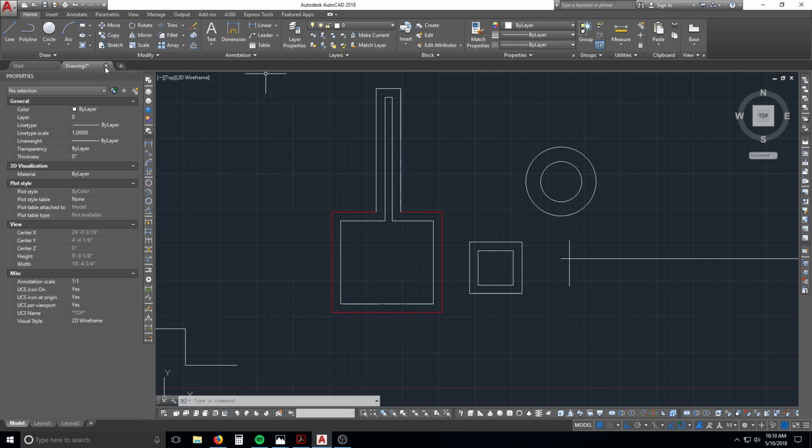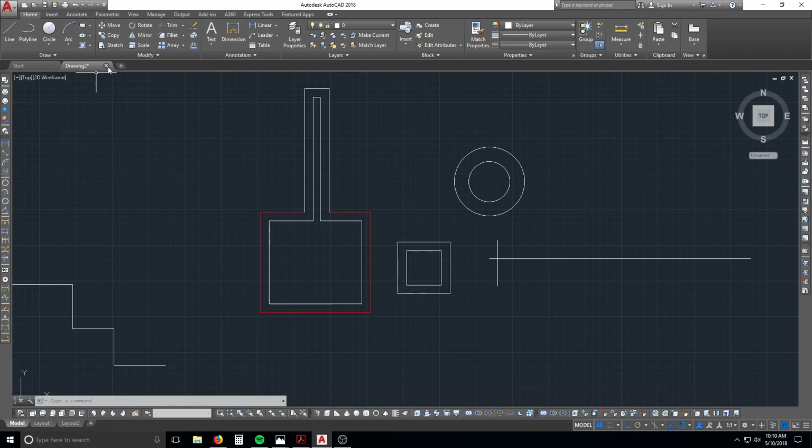Don't choose up here. This is new to 2016 and 18 or whatever, or 17. I've screwed that up a couple times. Down here, make sure you're directly across from the word properties, then you close. If you close that up there, you're closing the whole drawing. If you want to, guys, go ahead and hit the save button. That way if something happens, good thing to do. You can set these save intervals up for 1 minute, 5 minutes, an hour, 1 day, whatever.